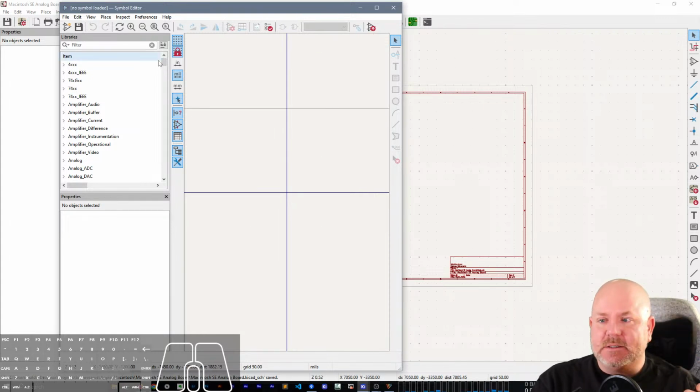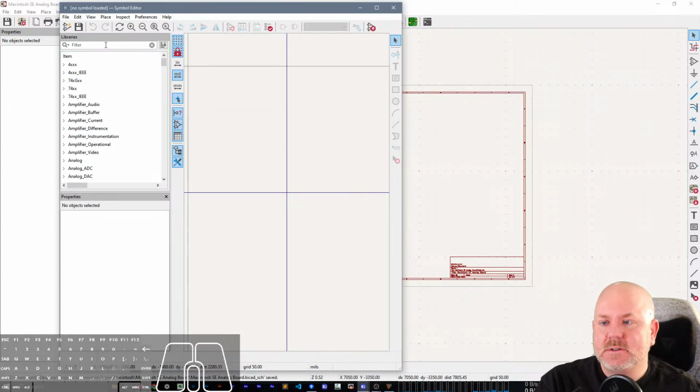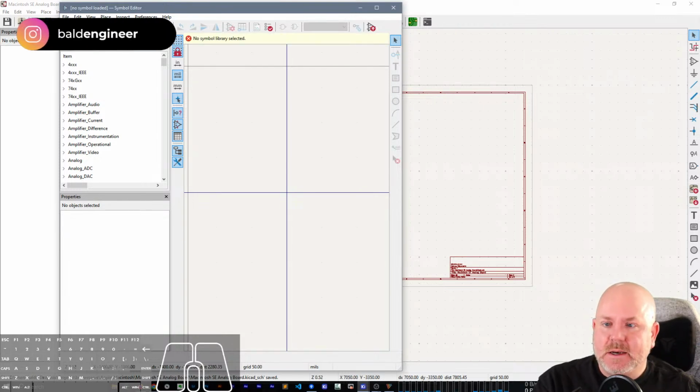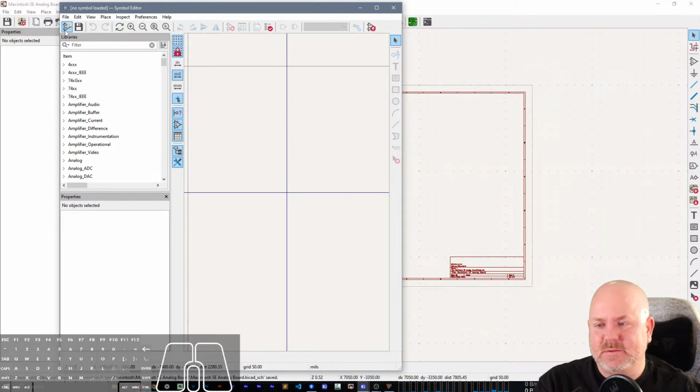Even though starting with KiCad 6, individual symbol libraries for a project aren't nearly as critical, especially in something like this, because the symbols get stored as part of the schematic now. Version 5 and before, there was a copy in the schematic, but it was linked to the library. It was kind of a mess.